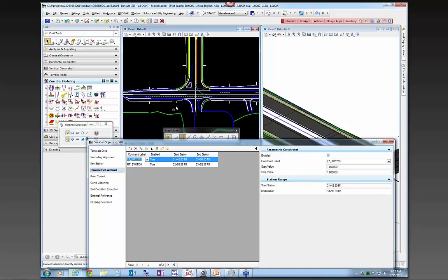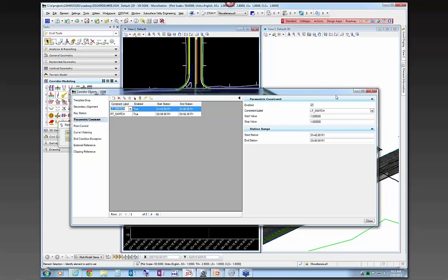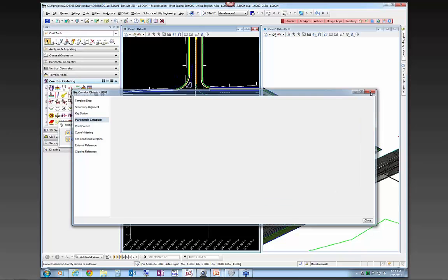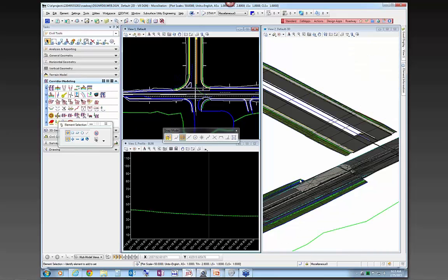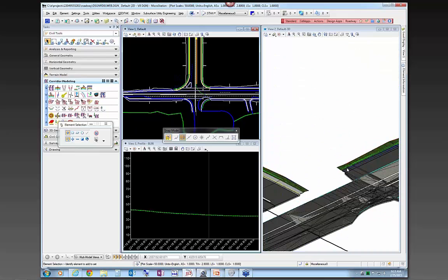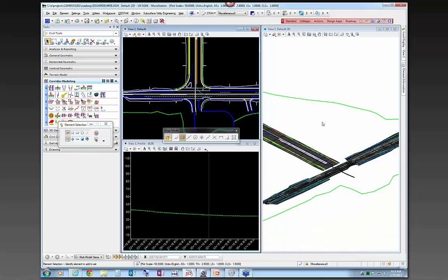And then on the right side it goes from this radius point to that radius point. And what that's essentially doing is giving me a gap to put in my intersection. And if we zoom in close, you'll see that there's no longer a shoulder, an unpaved shoulder, and then the tie down slope there. And there's no longer one on this side either. And then the same thing on this side. So now I've planned for putting this intersection in here.